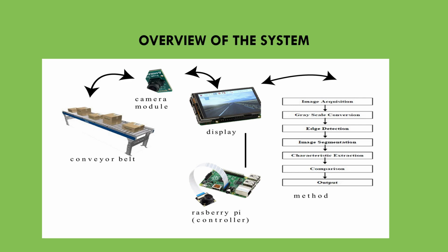The extracted features are fed into a recognition process and a decision-making system for grade rejection decisions. The locations in coordinates of the defects generated by a defect allocation function are combined with defect rejection decisions and user parameters to signal appropriate mechanical actions, such as to separate objects with defects from those that are defect-free.